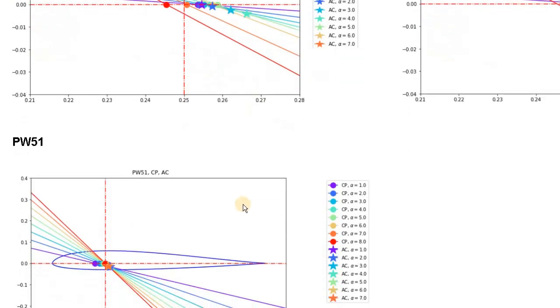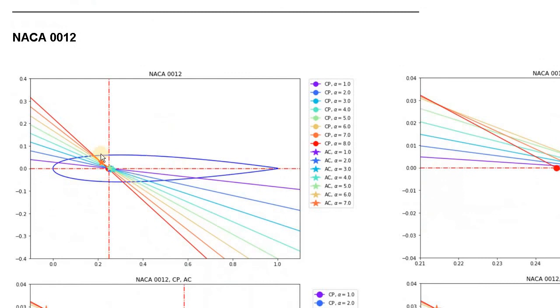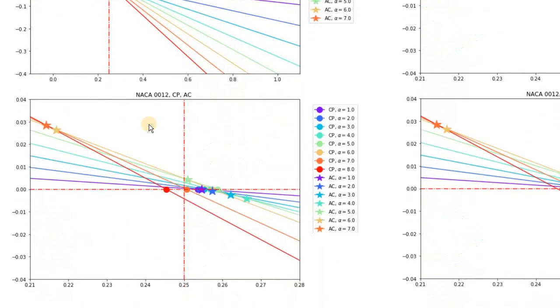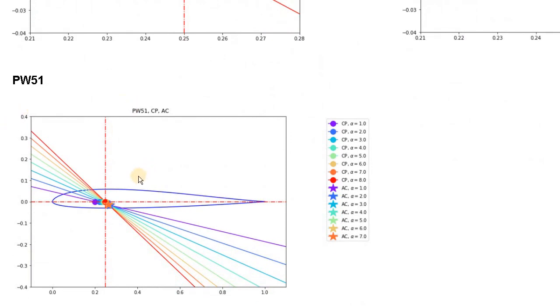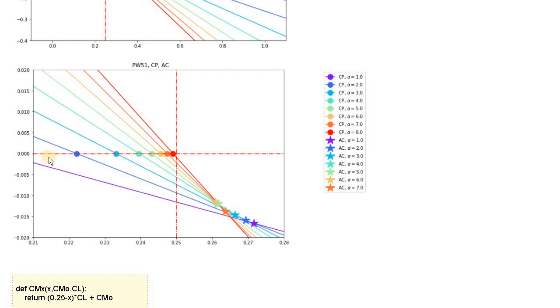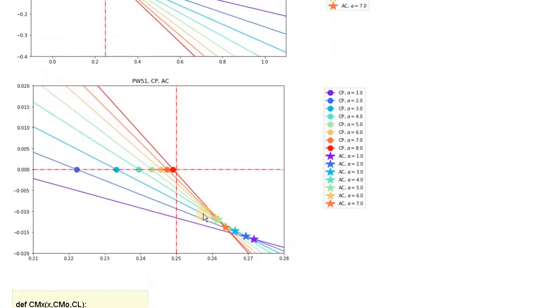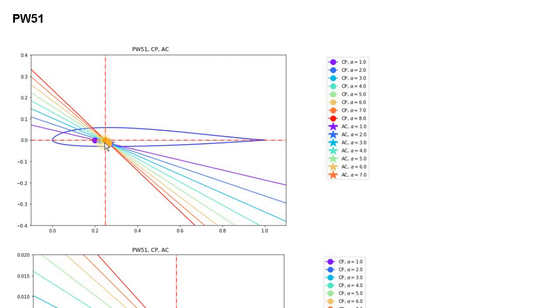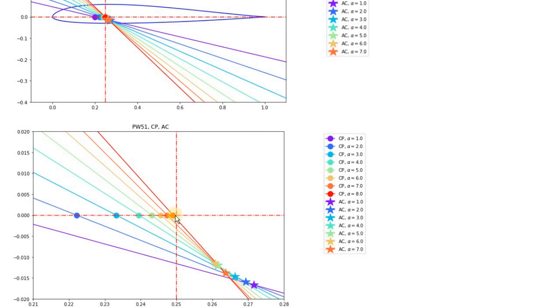And also we can look at different types of airfoils. Let's say this is the NACA airfoil, and the position of the center of pressure and aerodynamic center is close to the quarter of the chord of this airfoil. But if you look at different airfoils, let's say this airfoil is designed for flying wings, in the case of this airfoil you have a bit different position of the center of pressure and aerodynamic center. To be more precise, here's the position of the center of pressure. It's in front of the quarter of the chord, and the aerodynamic center is positioned behind this point. So in my view, this is a more stable configuration. Maybe I'll talk about this in my next video. But the conclusion is that the quarter of the chord is a good reference point. You might have your center of pressure position exactly there or somewhere else nearby, and the aerodynamic focus also can be positioned in some different places.